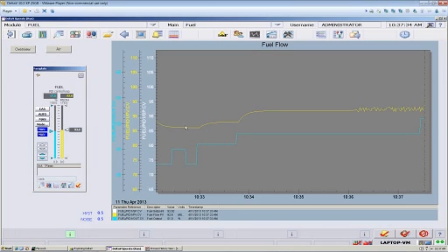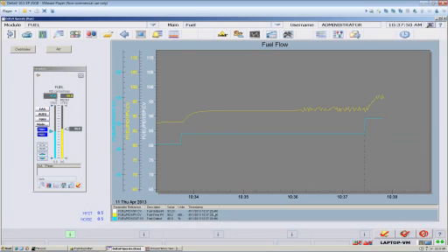Part of what I want you to see is we don't need a whole lot of math, especially if you have a nice charting tool like this. We can use just eyeball estimates and mouse clicks to quickly get our information. So like before, I can see right here, I commanded my valve to move at 10:37 and 26 seconds. Right here, by my eyeball estimate, I think that's where the dead time ended. We're kind of having to pick through the noise, and on average, where did this flat line end and this upward slope begin? 10:37 and 30 seconds. I'm estimating 3 seconds of dead time.